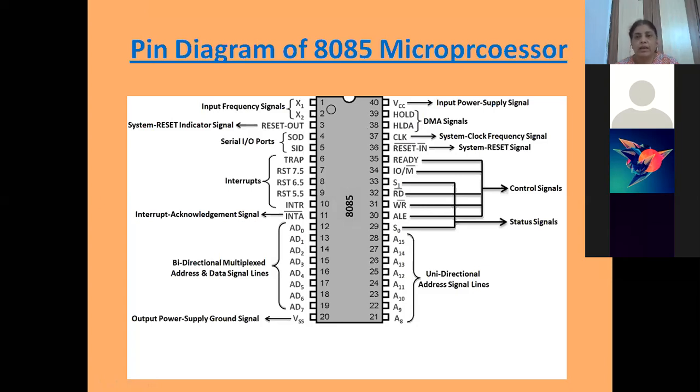क्योंकि as we have discussed that if we are transferring data and if we are not doing any processing, then there is no use of involving processor in the data transfer. So what we can do, we can transfer data directly with the help of DMA controller. But for that, DMA needs address and data buses, and that address and data buses are with 8085 microprocessor, because control of buses is with microprocessor only.